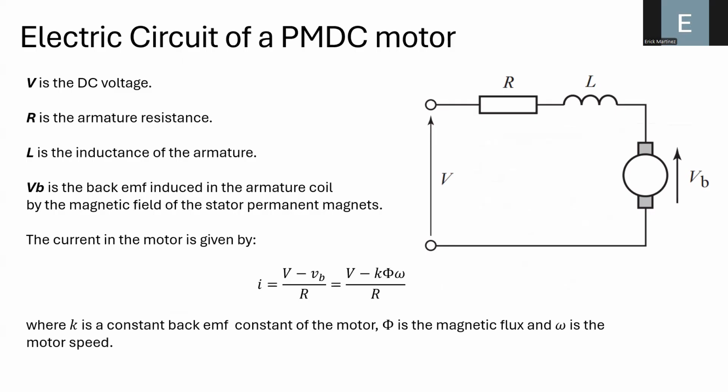By considering this, if we want to analyze these electric DC motors, we typically can use the following circuit, in which we have a resistance. This resistance basically represents the electrical resistance of the cables, these windings in the rotor. Also, these coils or windings can be understood as inductors, which is why we place this symbol for the inductance, which has a value of L.